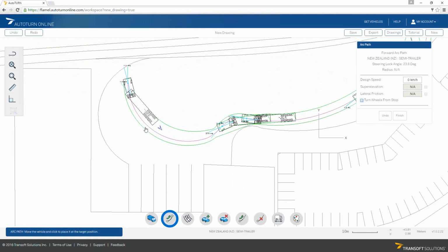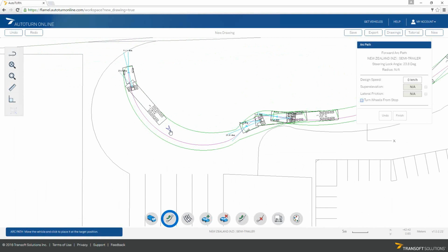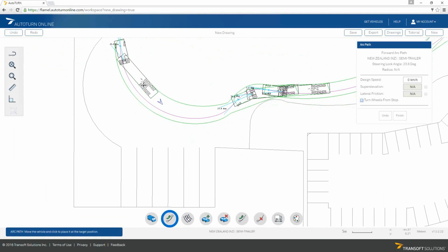I'm going to zoom in so that you can see there's a blue arrow here at the back of the vehicle indicating that the reverse maneuver can be triggered here. This is displayed at every section, so at any point in time you can choose to go in reverse just by clicking here, and then it's just a matter of dragging the vehicle to the loading dock we want. So let's say in this case I want to bring this one all the way over here. So I click here, and then I keep dragging the vehicle, and that's how easy it is, and we can produce our sections.